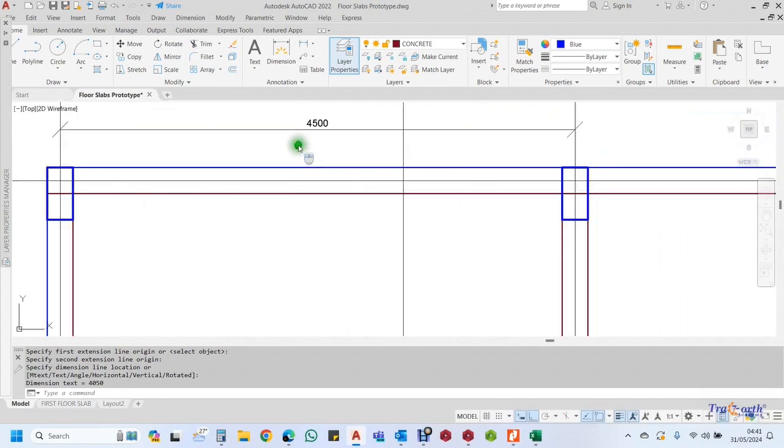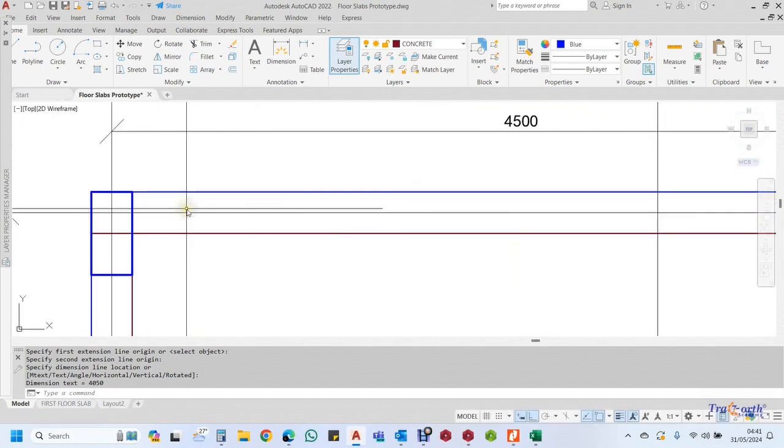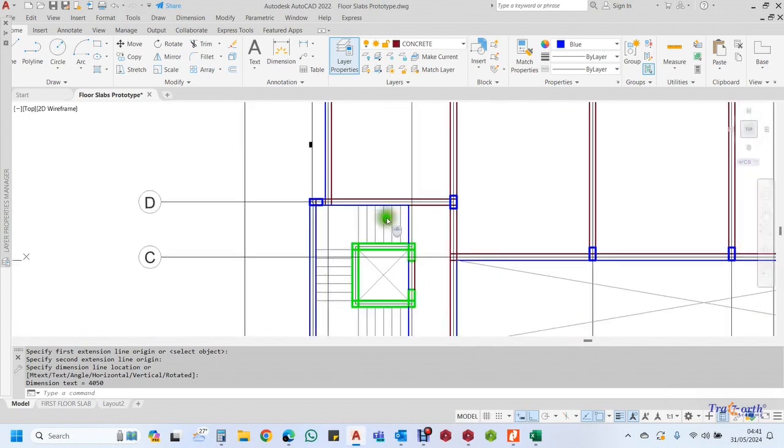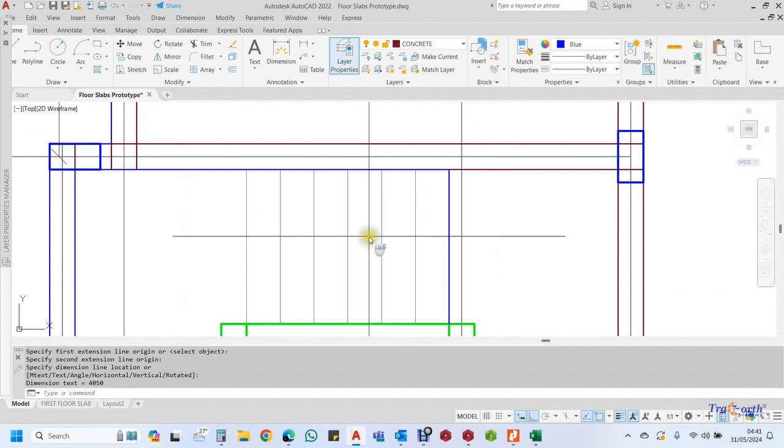So the edge conditions, the edge coefficient is what? Here, alongside, there is what? Discontinuous. Also, an edge can be discontinuous when the continuity of the slab is not up to half. Then they take it from half, but it's also advisable you leave it for more than half.